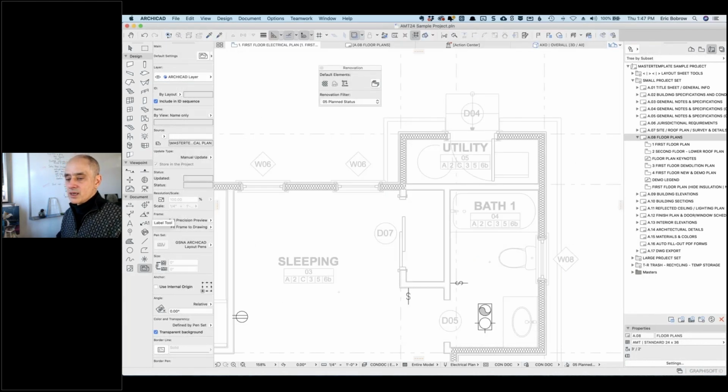All right. And Dave Yoakum says, I use duplicate PLN files after modeling the existing. So that is another strategy for remodel projects. And you could, of course, do it for something with multiple schemes. So in other words, you've got a base model, and then you copy the file. Now you have two files. Maybe you have them both open at the same time. You work on one, you work on the other. You can copy and paste things from one to the other.